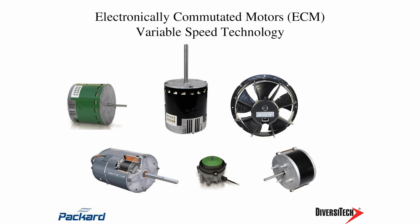So on these motors, one thing I love about these things that we can't do with PSCs as effectively is design them for the appropriate static pressure. So now my PSC design is essentially used for both condensers and for blowers.